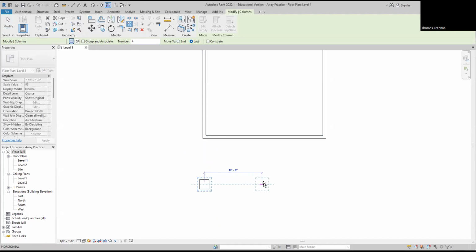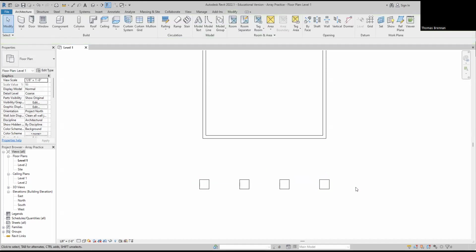We're just going to drag it straight over to the right until we see it lined up with the center line. Can you guys see that? When you see that, go ahead and click on it, and boom, there's your array. So you're able to create an array that simply. Again, multiple objects. It's like the copy command, only they're automatically spaced. They understand I'm going to be this far apart from each other, a total of 4, and it spaces those automatically, so you don't have to do the heavy lifting on that.